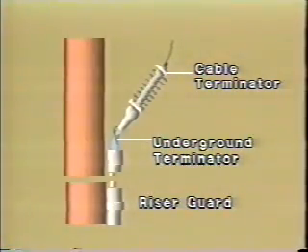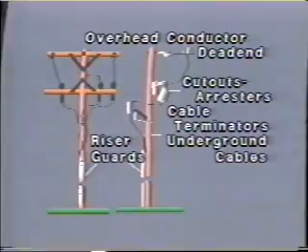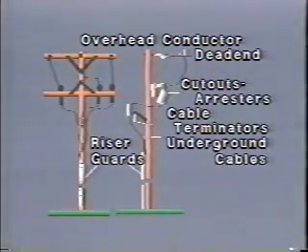The underground cable is then protected at the ground level of the pole by a steel or plastic cable guard. A three-phase overhead to underground dip pole differs from the single-phase assembly by the introduction of a second cross-arm to support the three cutout arrestors. The three cable terminators are mounted on a common bracket. The underground cables are protected by a single riser guard.